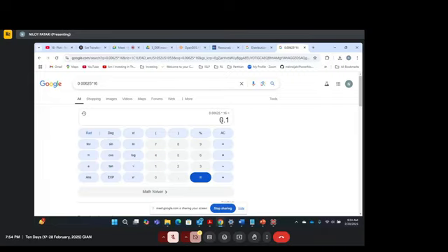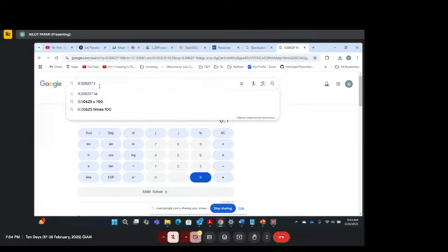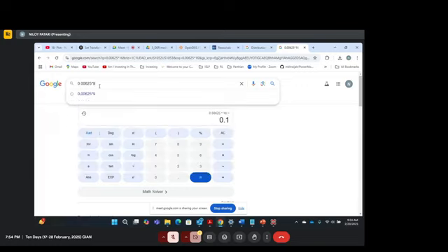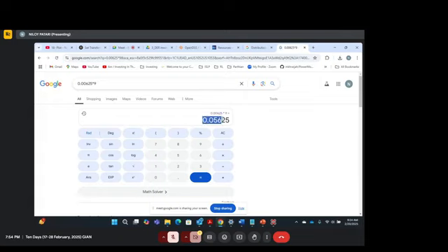So basically you have this 32 taps, and 32 taps will help you to boost up and boost down. So if you have 0.00625 multiplied by 9, this is the amount of per unit voltage that will get boosted, right?